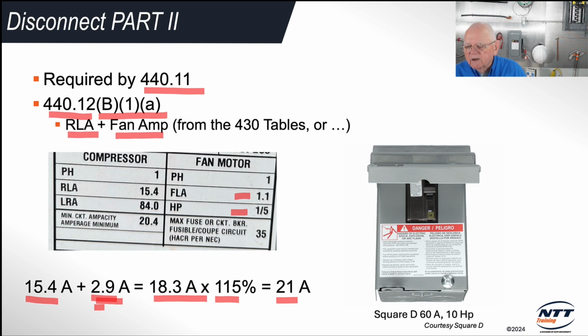Here's a picture of what I was talking about, typical switch. It looks like a circuit breaker, so we open up the enclosure cover mounted on the outside behind the condensing unit outside of the residence, whatever, commercial building. We take a look inside, oh, there's a circuit breaker. Must be another branch circuit. No, if you take a look at it, there's no number up here on the handle, no 20 or 35 or anything like that. And then there's a little nameplate over here, a little tab actually, and it says no overcurrent protection provided. This is a switch only. So that's what it is. It's a switch. Looks like a double pole 240 circuit breaker. It's not. It's a double pole 240 volt listed switch.